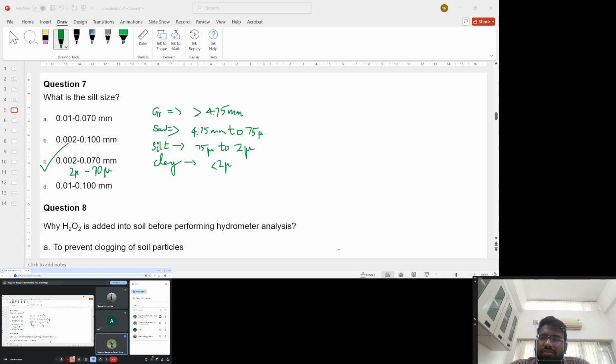Usually silts are kind of an intermediate material. Is it a good filler in compaction? To an extent, yes, higher particle packing, but since its permeability is very low, the pore pressure buildup will be high. So its dissipation of pore pressure will be low. So it is not as such suitable for backfilling also.